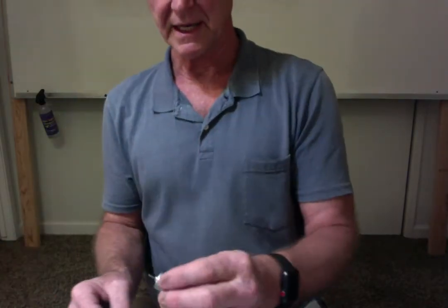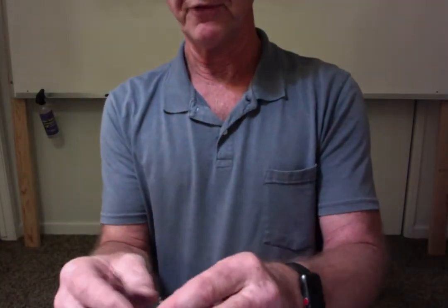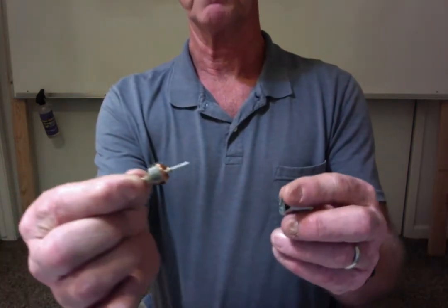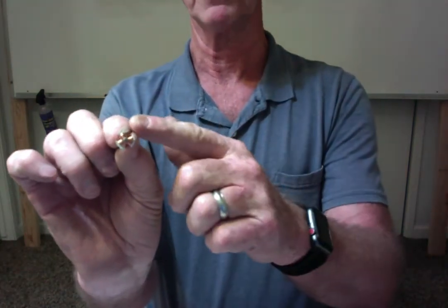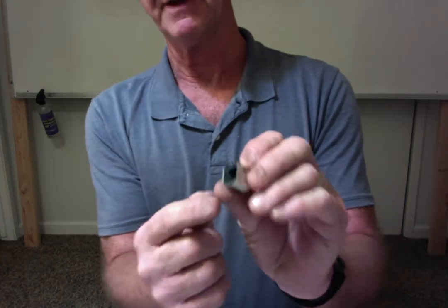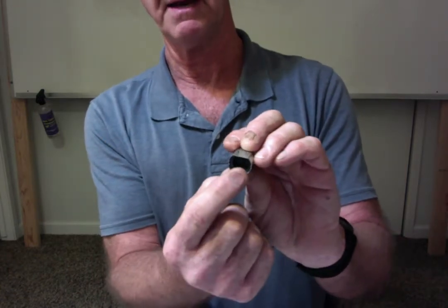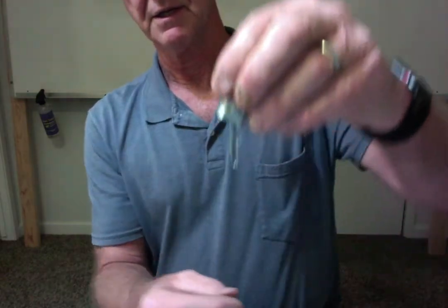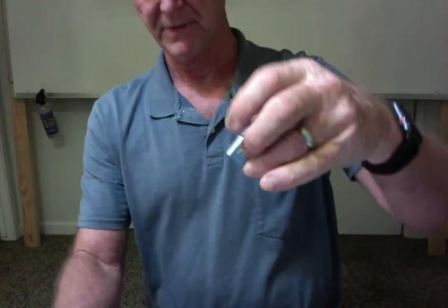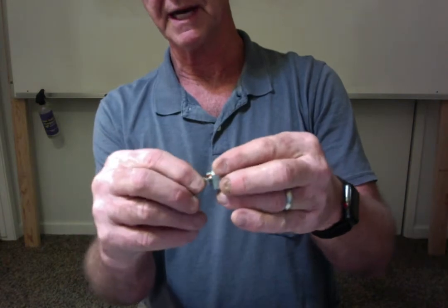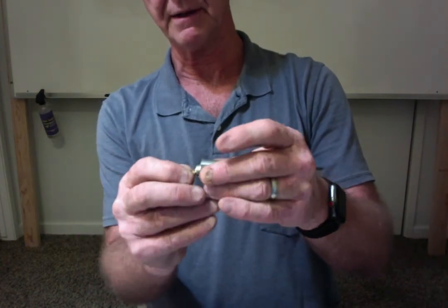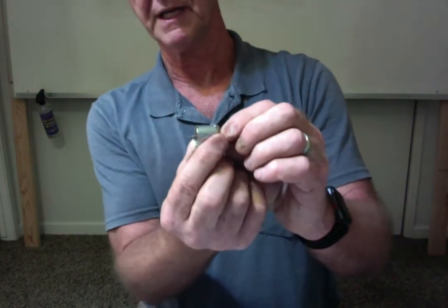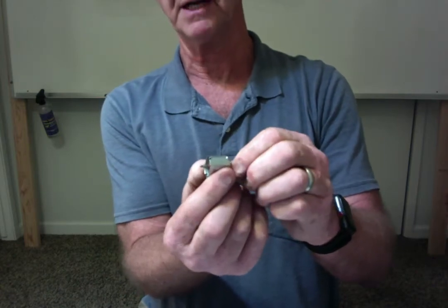The interesting thing about that motor, and I showed you this before, is that this motor is made up of a bunch of coils of wire, and inside of here there is a magnet. If I take, for instance, these paper clips, those paper clips will hang from there. So this coil sits inside of a magnetic field. Now think about it. When I turn this, I'm actually creating electricity.